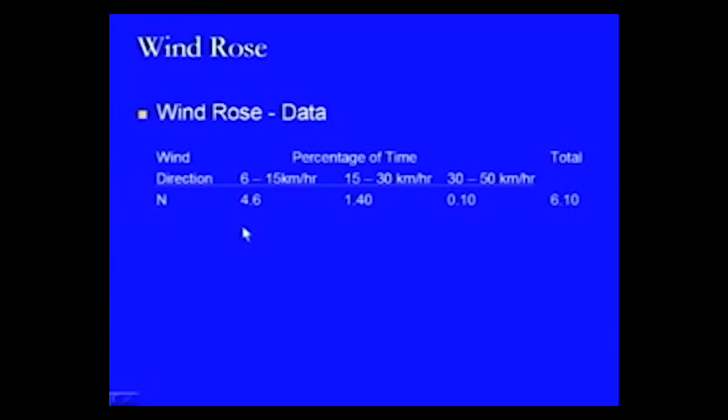So, that is how we have the composite data available in this form, which can be used either to draw the type 1 diagram of the windrose, where we use only the direction and the duration, that is the total duration, or we can draw the type 2 diagram where we use direction, duration and the speed, that is the intensity, defined here in this form.